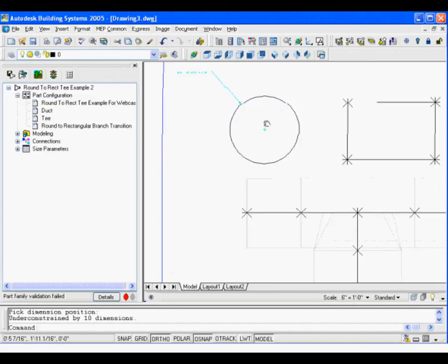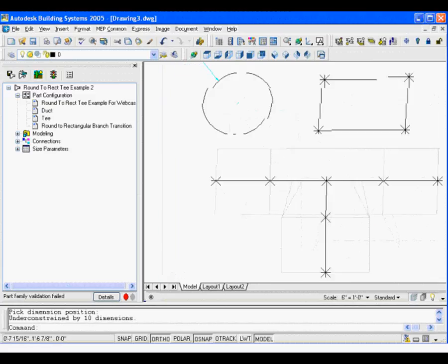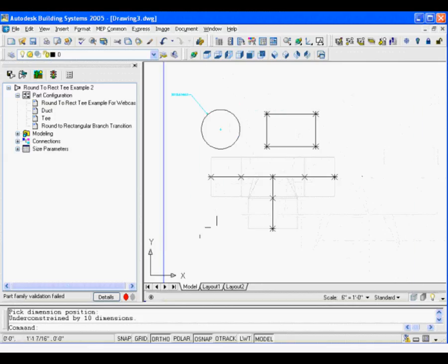D1 is going to be my connector size on that side of my T. Now, I can also add the connection on the other side, and you'll notice that I'm not going to get prompted for the dimension. The reason is because the modifier is from the same profile. If I click on here, all it's going to ask me for is the default connector number, number 2. It didn't ask me for the dimension because it knows that if this dimension changes, all 3 of these modifiers have a relationship that's been established with this profile. So it only gets dimensioned once.